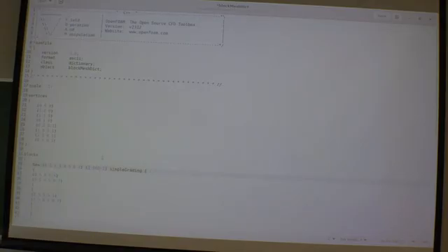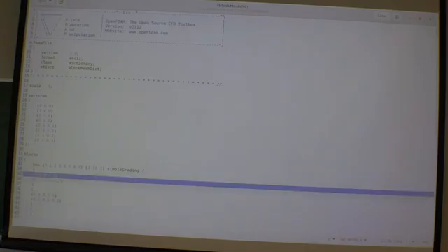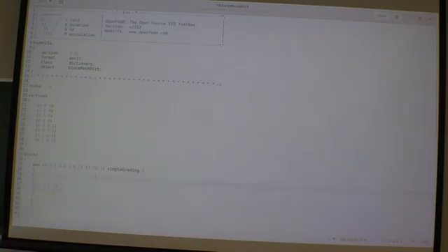Let's start easy here. I use only 10 cells in the Y direction from the wall and then to a symmetry line. Then I don't need this advanced stretching. You can hardly stretch anything with just one cell, so here I just have a 1.